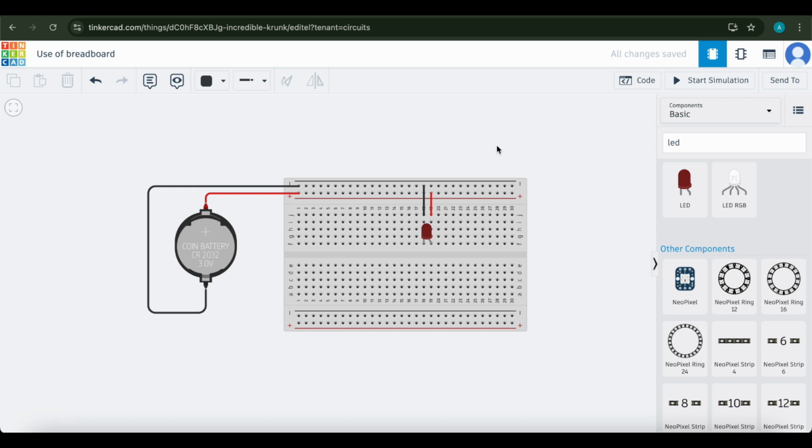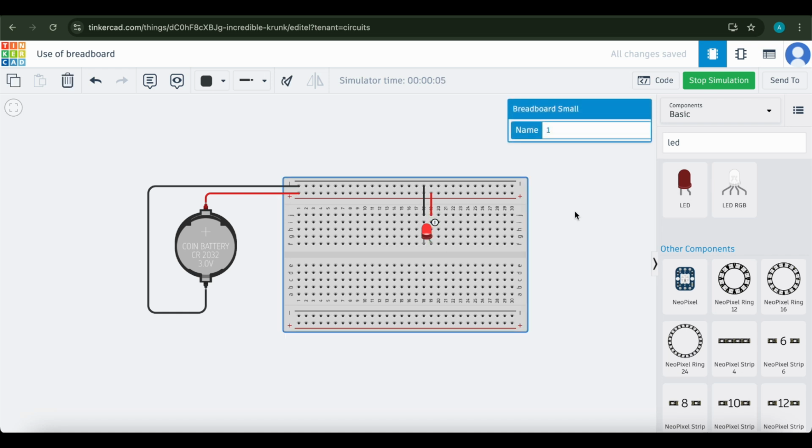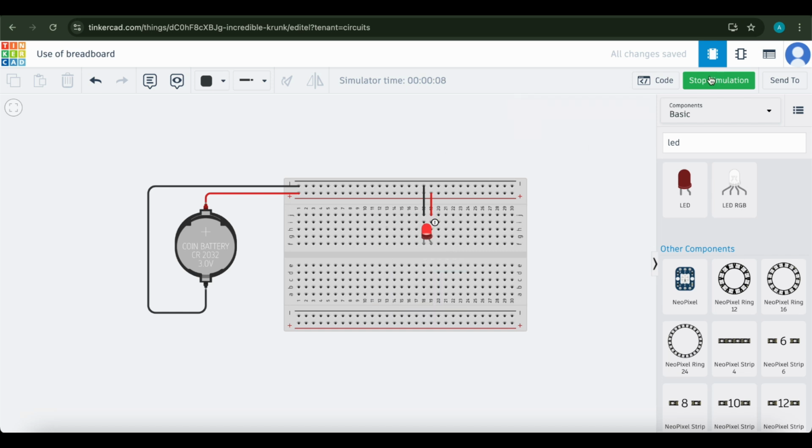But one thing is that in my last session I had told you, if you want to make use of an LED, it's always good to make use of a resistor, because it resists the flow of current. Your small LED doesn't want such a large amount of current. But let's just run this code first and see. Yeah, so you have a warning message which says it is having too much voltage. So we'll just stop the simulation.